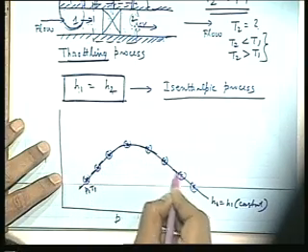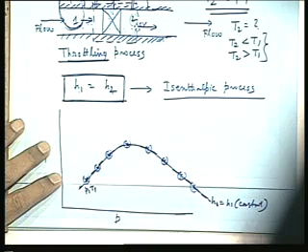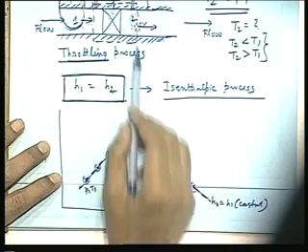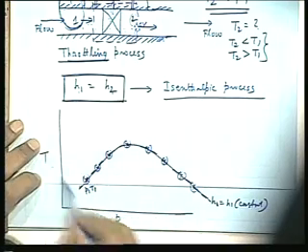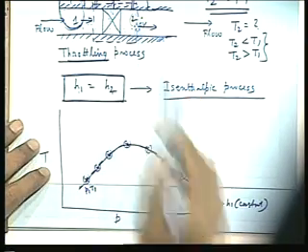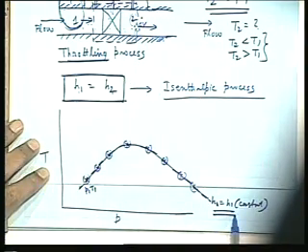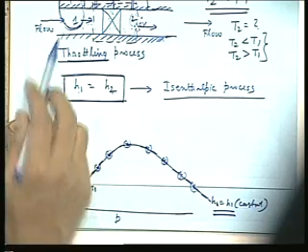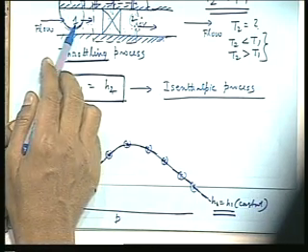Rather, this shows a curve of the same enthalpy, that means the locus of equal enthalpy points. That means I can generate a number of pairs of P and T points whose enthalpy equals the enthalpy H1, which is the enthalpy corresponding to the initial state P1 and T1.